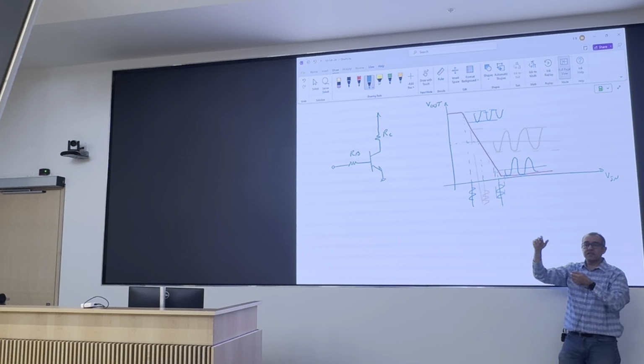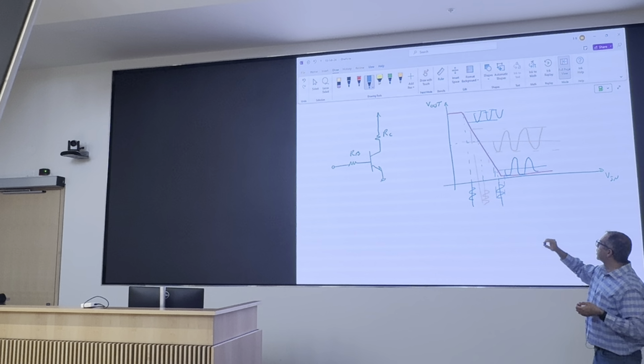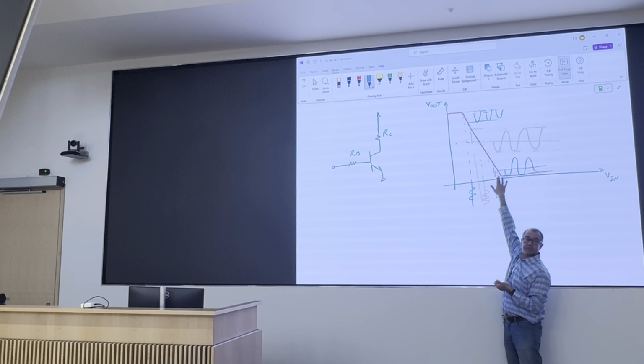But if it is early, let's say right after this microphone, which is producing, let's say, microvolts of signal, going into, I don't know, some ADC afterwards, I don't need 10. If I get it up to, let's say, 100 millivolts, that's good enough for me. So what I can do is bias my transistor down here. Because you'll see in a second, if your device is down here, you get more gain out. So for gain reasons, you put your VCE here. But biasing, again, is different. So you may use the same current, but you choose different VCEs.